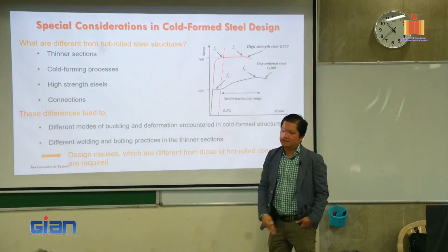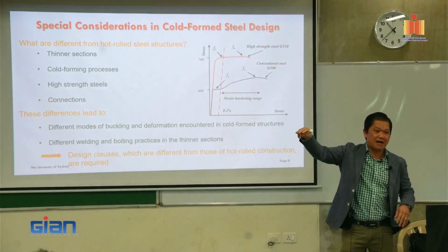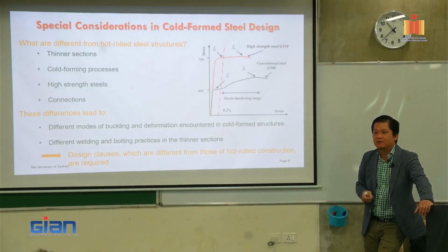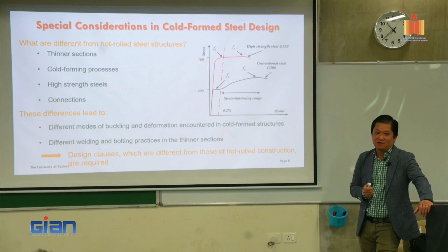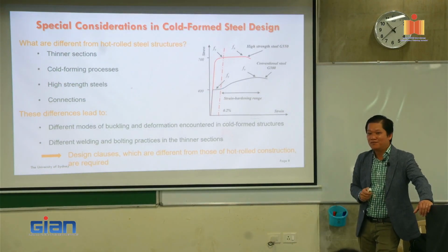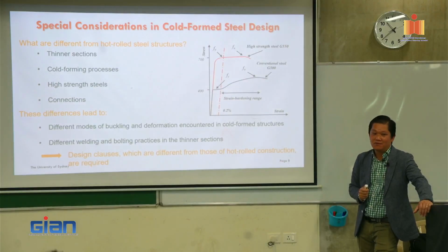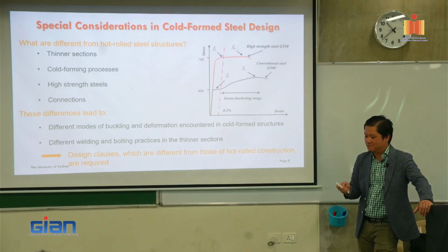With the normal strength steel, you know that because of the strain hardening, FU is increased a bit. So FU is very important, as you can see, to design for connection. Right? We use FU a lot, not more for member capacity, but for connection. We use FU.